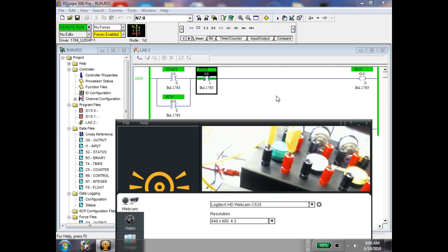The problem we have with people learning this as a normally closed contact is that it's not a normally closed contact, it's an examine if open instruction. But we want this guy to be true when we come up here and start this. So let's show what happens.